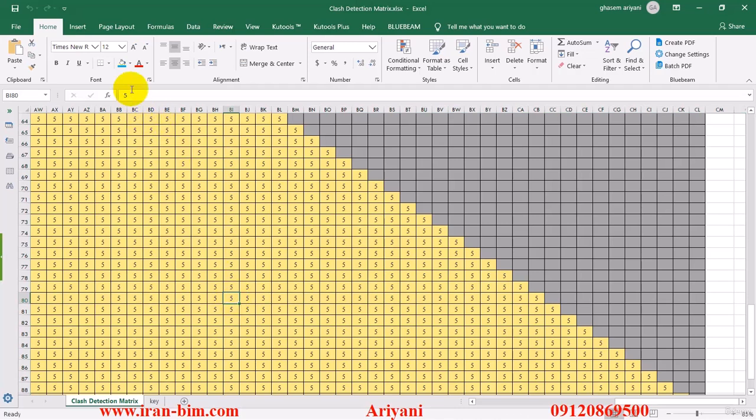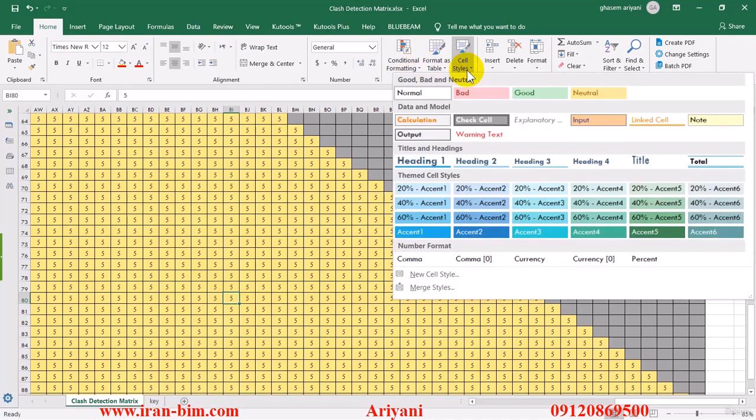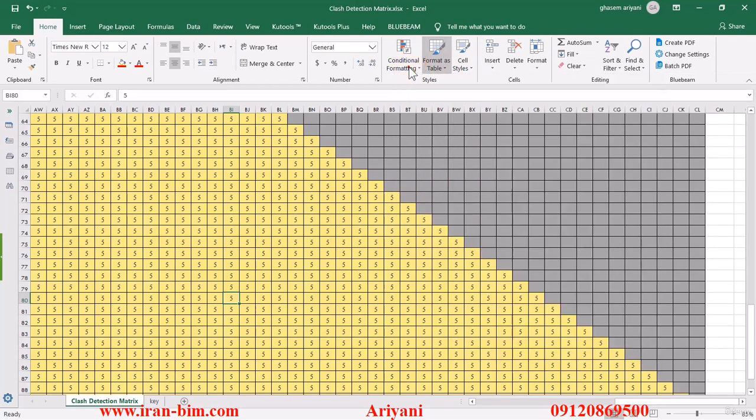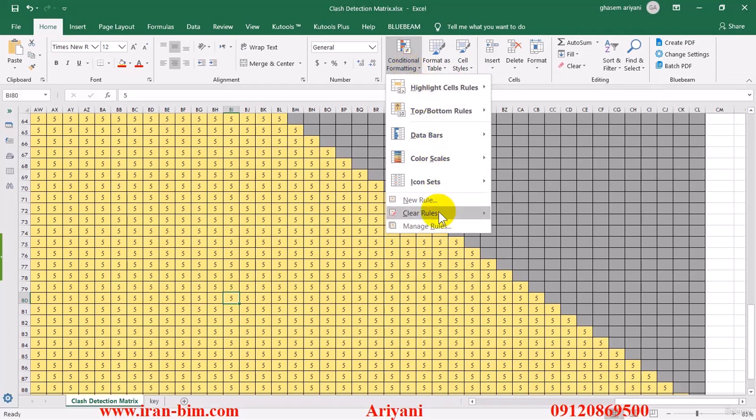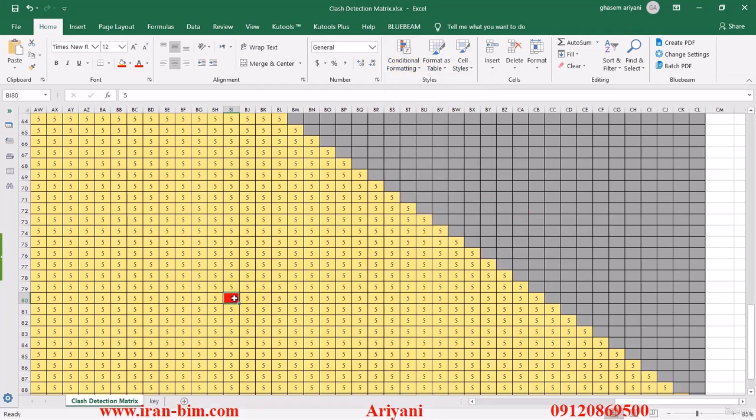Now, in order to identify this, I can select a bracket and turn its color to red because it's one of our hard clashes. Although I've already selected a different coloring format and pattern for this, as you can see here, and so I'll have to first clear the color of this, and then for the bracket itself, I'll put in the tolerance that we've used, which is 100th.